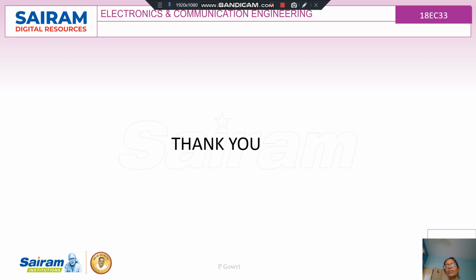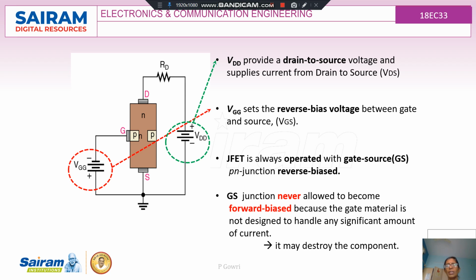In this video we have discussed what is meant by a JFET. As a recap, the JFET consists of three terminals: gate, drain and source. Also, we will always have two supply voltages, one to reverse bias the gate terminal and another to supply the drain current. The drain current is always from the drain to the source. Again, the drain and source are interchangeable, so those terminals can be interchanged.